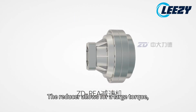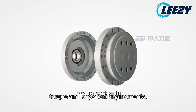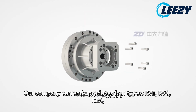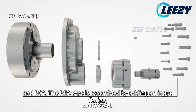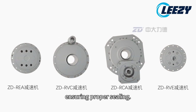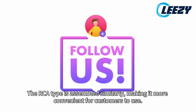The reducer allows for a large torque, capable of withstanding more than 3 times the rated torque and large bending moments. Our company currently produces 4 types: RVE, RVC, RE, and RCA. The RE type is assembled by adding an input flange, rear end cover gasket, and grease to the RVE type, ensuring proper sealing. The RCA type is assembled similarly, making it more convenient for customers to use.